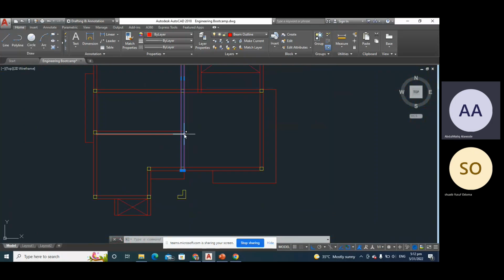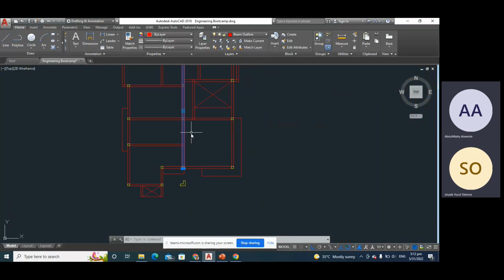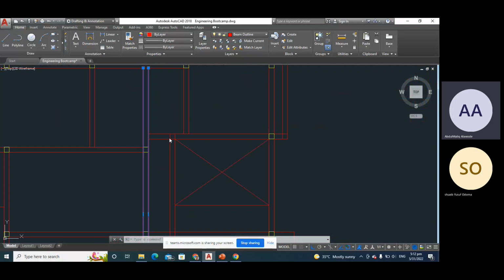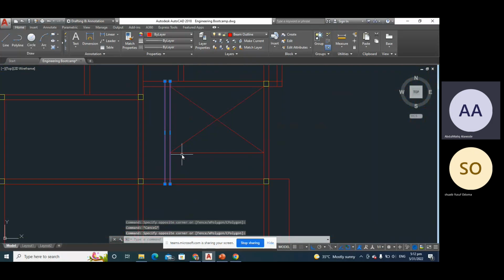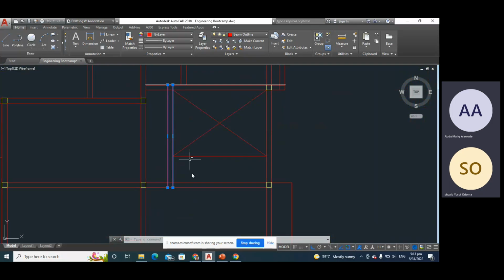But at this point, this beam that my cursor is highlighting is going to have a secondary beam on it, because it is this vertical beam that I've highlighted that is going to be supporting this horizontal beam. That's the support system for that beam. Now this beam, how is it going to be supported? It is a simply supported beam. It's going to be supported by this beam and also by this beam. Just one span, supported at the two ends by beams.